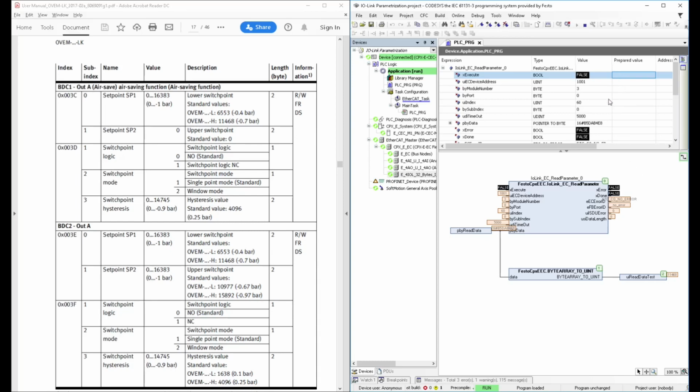What if there was an error? For example, oh, you know what? I made a mistake and I put in port number 2, which we know is not enabled. Remember, this is the IO-Link port, right? I have 4 on that module. Port 2 is not enabled because we didn't enable it here in the startup parameters. So let's see what happens if I try to read from port 2. I execute, and it's going to time out, I believe. The timeout is 5 seconds. So there you go. Error, timeout. I can't read from that port. Okay, let's change this back again to 0 and try to read again.